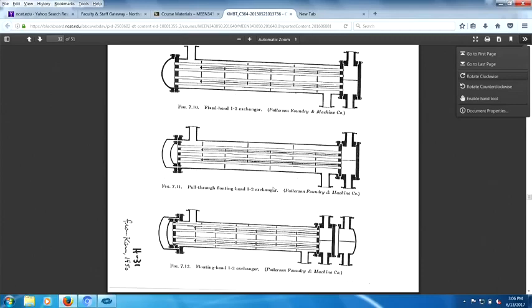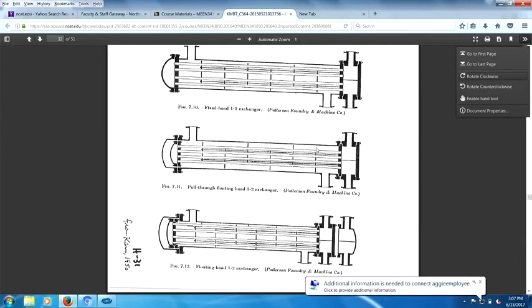Right. Nope, not everything's wonderful here at all, because the shell is being wasted. See, this thing's going to cost you $1 million, so you want to have it as efficient as possible. You have this shell volume in here that has no heat transfer surface in it. So you're wasting money here, gang. Then you pop down to this job.